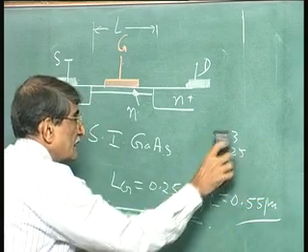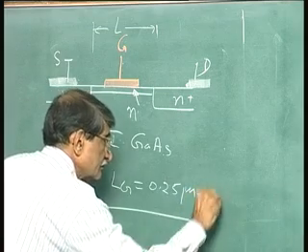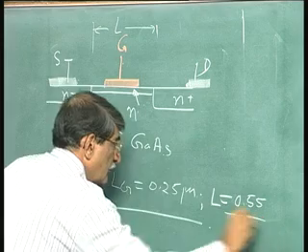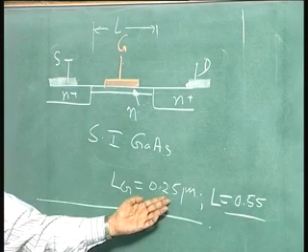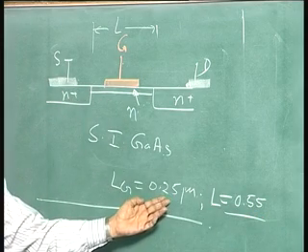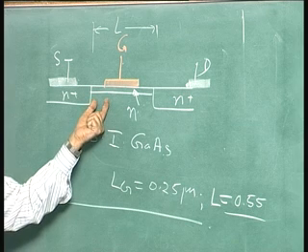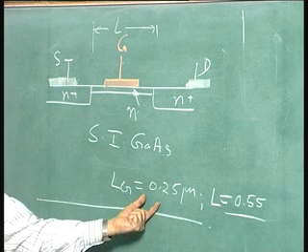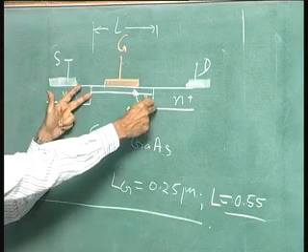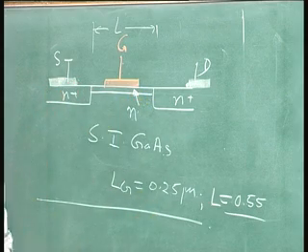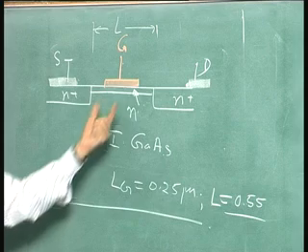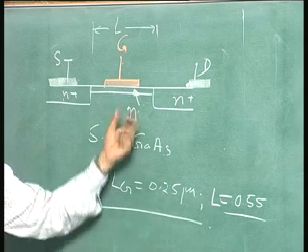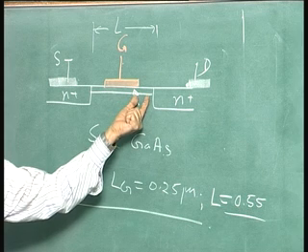Okay. That is what you get. Whereas in the other case, 0.3 plus 0.3, 0.6, plus 0.25, 0.85 micron. So, you have got 0.85 micron in one case, in another case 0.55 micron for the same channel length, gate length. So, the fields are much higher when the L is 0.55 micron.